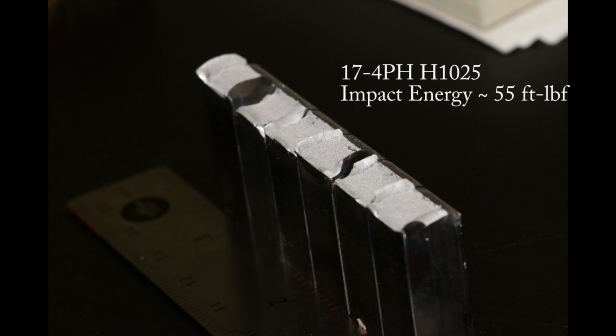And if you go back and listen to the clip again, you'll hear that the sound the sample made when it broke was much deeper than the H900 condition sample. And likewise, when we look at the fractured surfaces of the samples, we see that the shear lips are much larger than they were in the H900 condition samples, indicating that the sample is going through much more deformation across the entire surface of the sample and is able to absorb more energy.